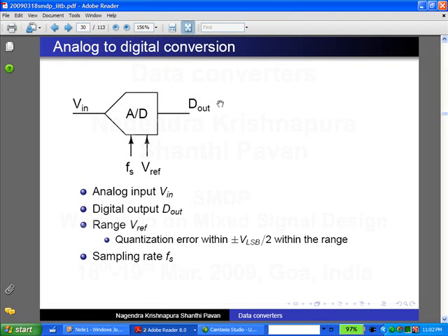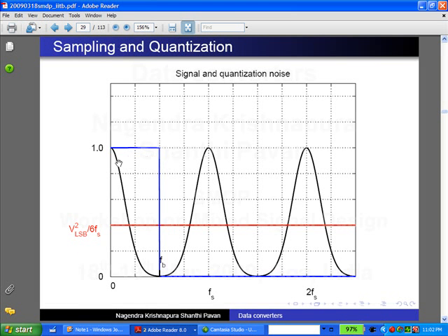No, it should not change at all. It should be simply a copy of the signal. It will be the same. What will happen is, you will get this black part which is the signal and this red part which is the error. When you take more levels, this red part will go down. The black part is your original signal, that will remain the same. Whatever junk you add to it will keep on changing depending on the number of levels you have. Is that okay?